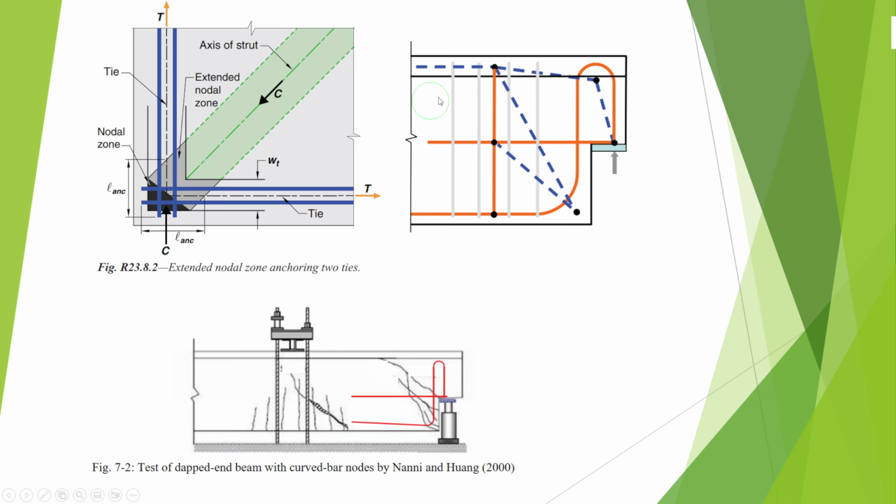So you will transfer a huge load from the beam to the supporting edge. So we have to make sure that this reinforcement is safe against bearing pressure and bearing stress in these areas.